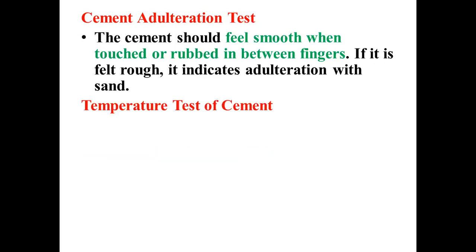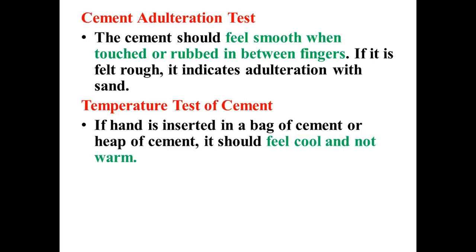Then the temperature test on cement. We put a hand inside the bag of cement, and we have to get a cool feeling. If the hand is inserted in a bag or heap of cement, it should feel cool and not warm. We cannot get a warm feeling; we always have to get a cool feeling. Then the quality of the cement is good.